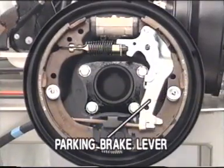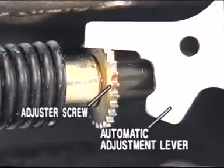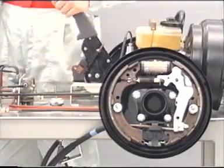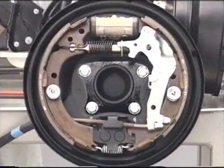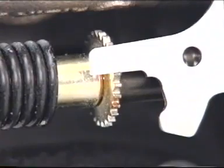When the parking brake is applied, the lever is pulled to the left. If there is excessive brake shoe clearance, the adjuster lever would go over the adjuster screw notch. When the parking brake is released, the adjuster screw rotates and adjusts the brake shoe clearance.